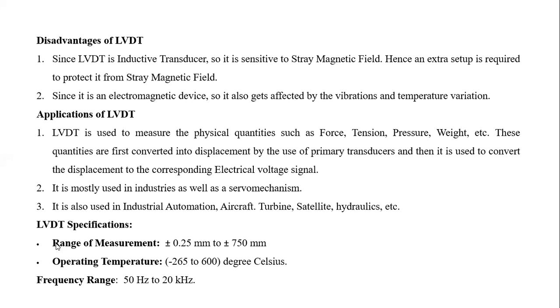The specifications of LVDT: the measurable range is plus minus 0.25 mm to plus minus 750 mm. Operating frequency is 50 hertz to 20 kilohertz, and operating temperature is minus 265 to 600 degrees Celsius.